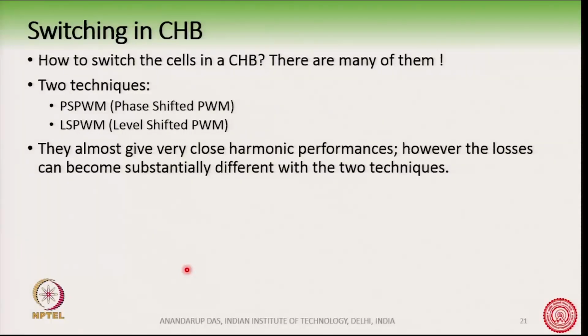Now, focus on these 2 techniques, phase shifted PWM and level shifted PWM. Basically, both these techniques are very similar. It is just that the approach is a little bit different. So, their harmonic performances are also very similar. Level shift PWM gives a slightly better harmonic performance. However, for any level, like more than 5 levels, this hardly matters.